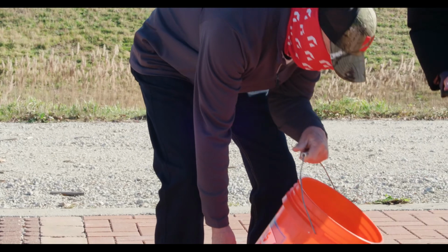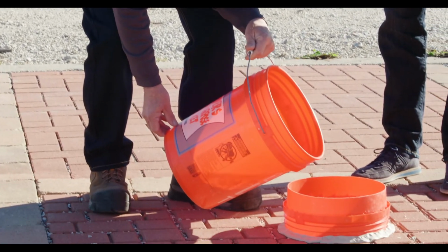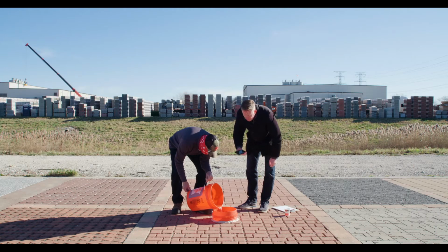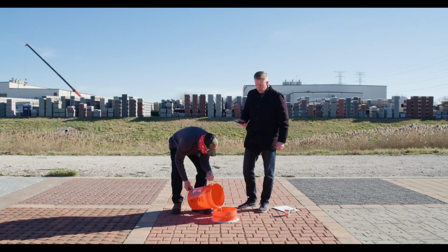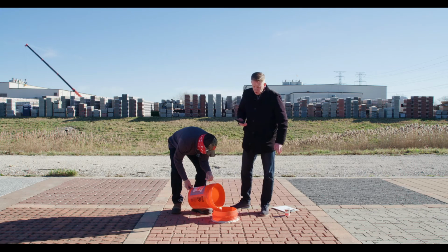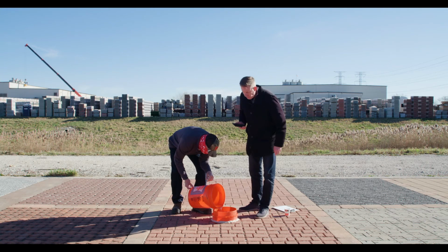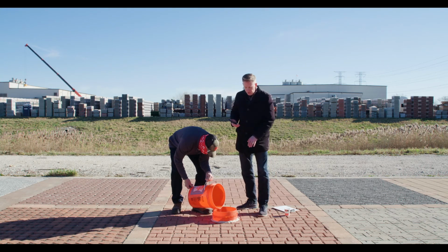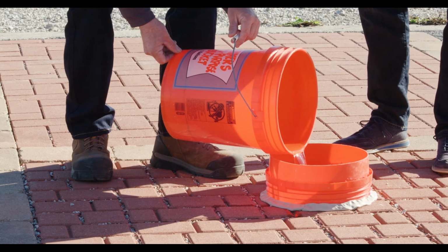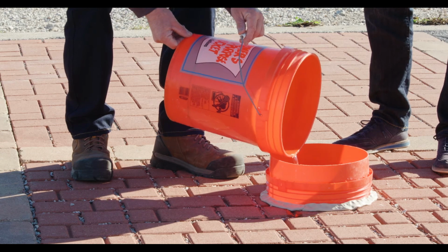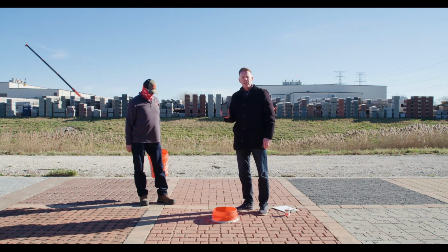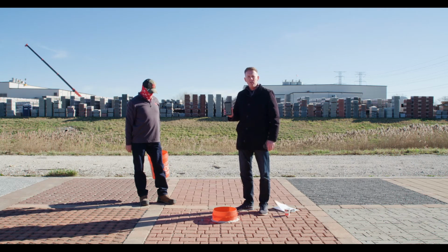Now sometimes you might experience some bleed out where the water will drain out. It shouldn't be too critical, like we see some here on this side. It's still draining through the pavement very quickly. And stop. It took 25 seconds for the 8 pounds of water to drain through the surface.